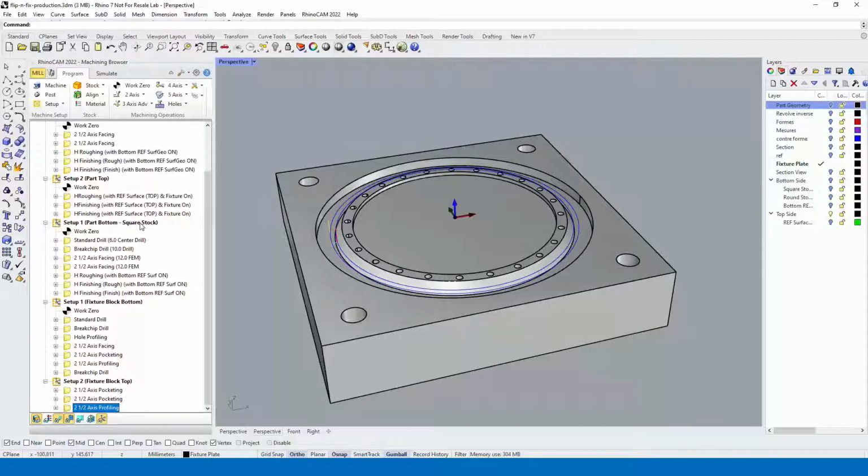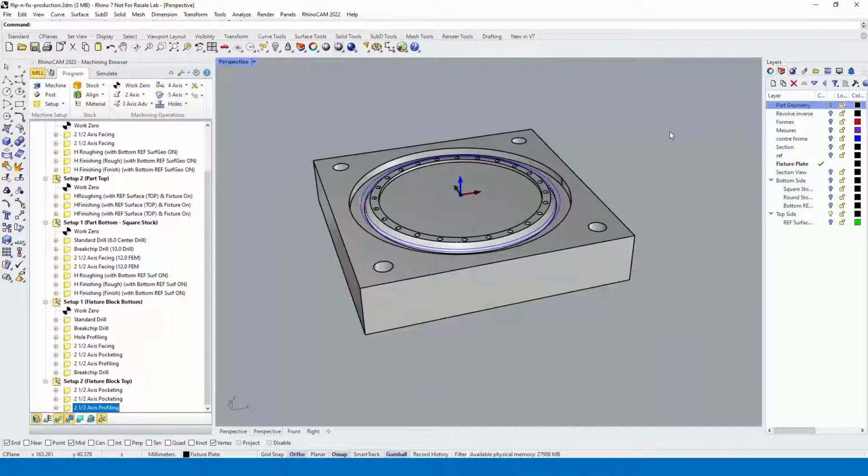Yeah, one other technique that you can use for positioning the part after you flip it is these registration pins, which Don talked about briefly here. So there's holes on the 4 sides. You can actually set up registration pins for your part on the stock model. And then when you flip it, you stick it back into those registration pins, and that way the dimensions will be correct in terms of machining from either side. So that's another technique that people use.